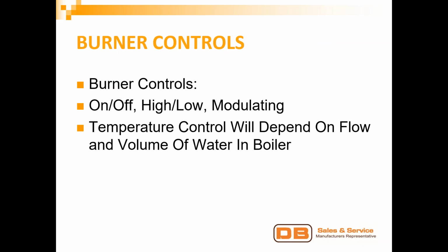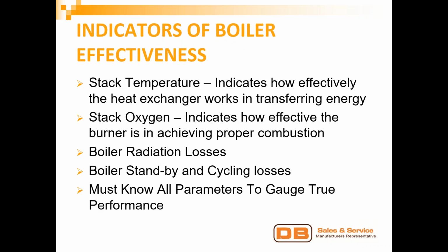Then next we talk about burner controls. You have on-off burner controls, high-low, which are kind of a stage firing or step firing, and then modulating type controls. And temperature control will depend on the flow and volume of water in the boiler. Those are all important factors to consider when looking at your different types of boilers.